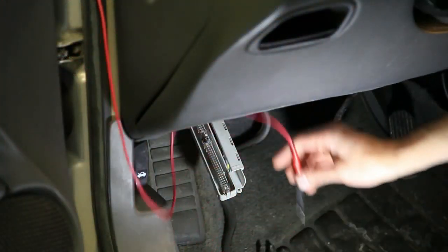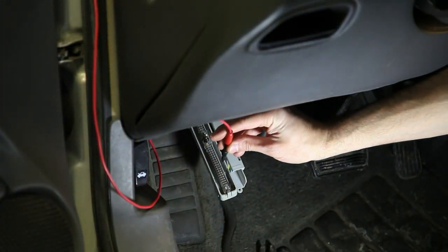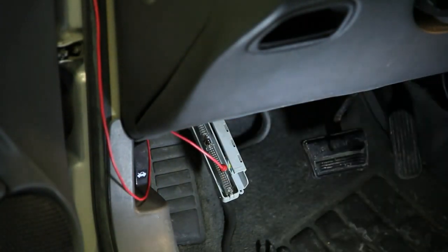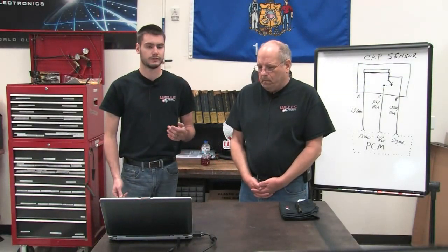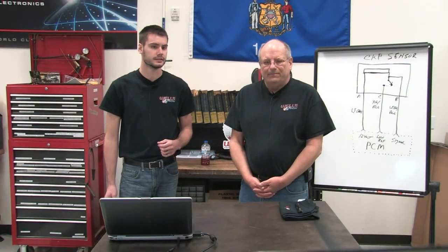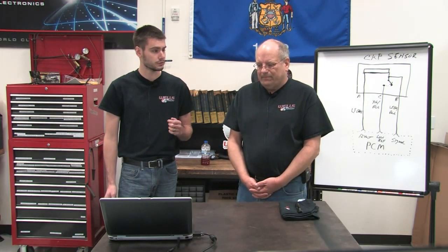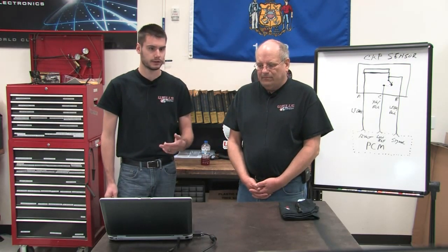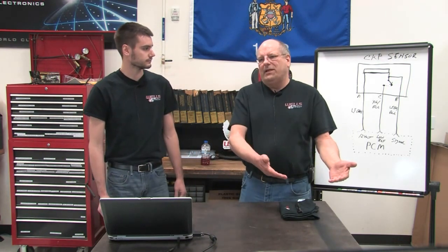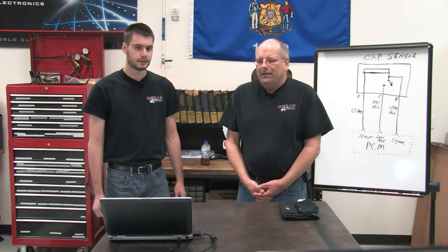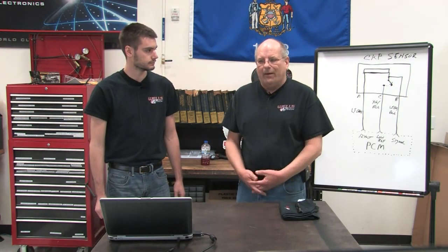So, what was our next step? Well, I went to the PCM then and actually went to pin number 72 and checked the voltage coming directly out of the PCM. I thought maybe there's high resistance in the wire or something. Let's make sure the wiring's right. At the PCM, 11 volts. Okay, that's interesting. It's still 11 volts. So then check powers and grounds going to the PCM. Battery voltage and a good ground. We're all set. Everything going into the PCM looked right. What was coming out didn't. Exactly. So it appeared that we had a problem with that PCM.